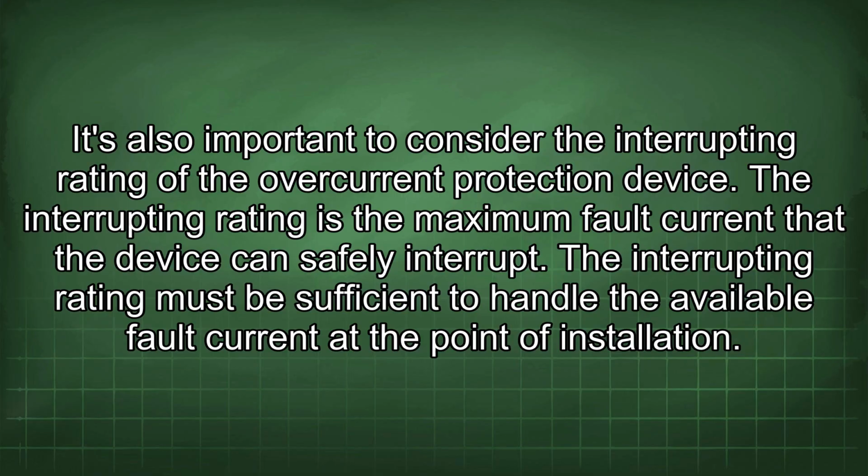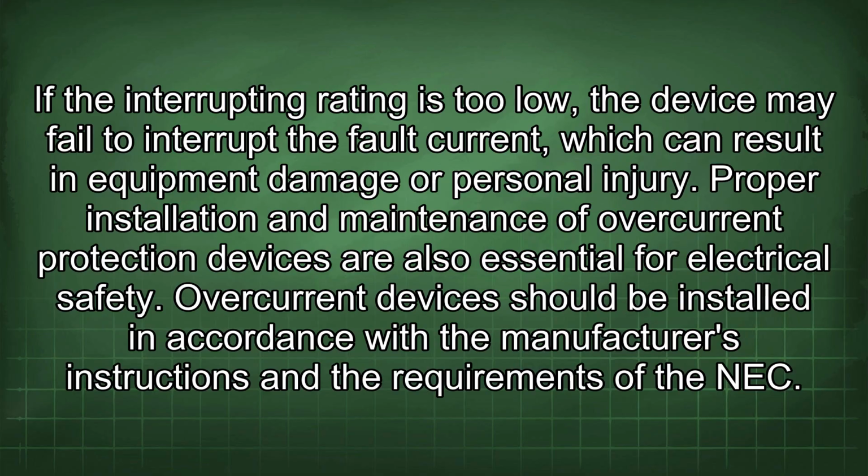The interrupting rating is the maximum fault current that the device can safely interrupt. The interrupting rating must be sufficient to handle the available fault current at the point of installation. If the interrupting rating is too low, the device may fail to interrupt the fault current, which can result in equipment damage or personal injury.